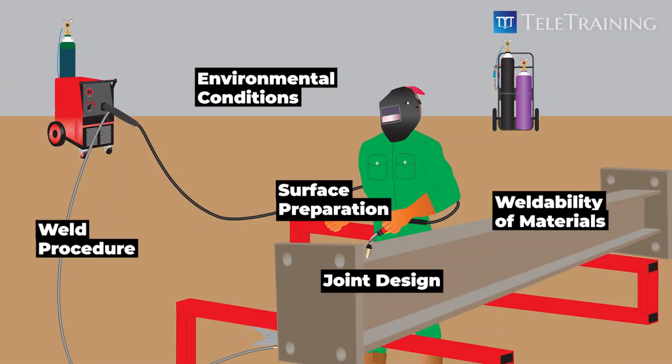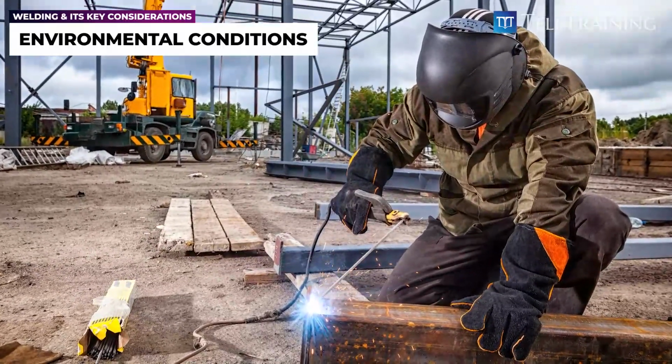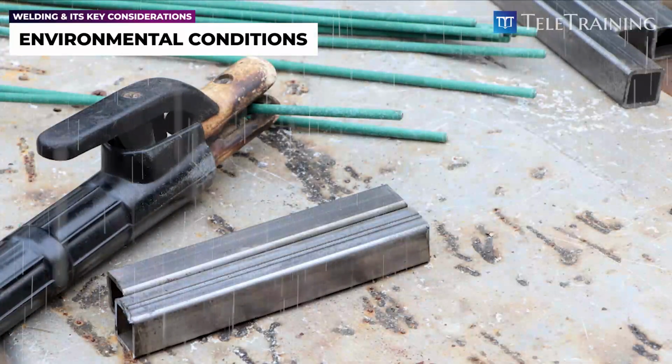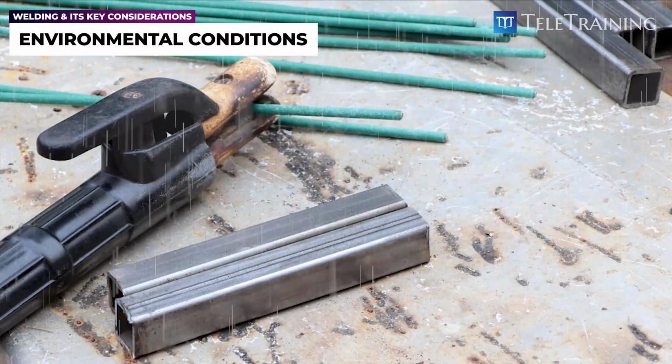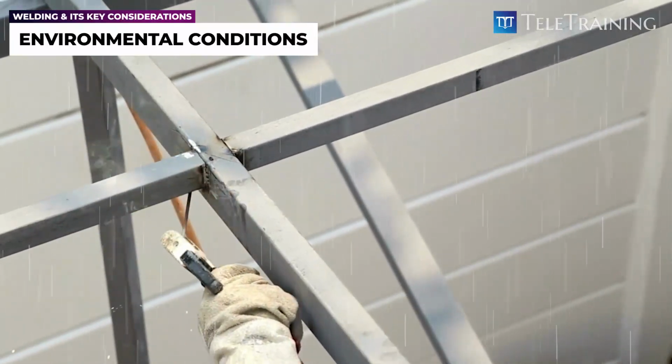The next is to consider environmental conditions. Environmental condition is a very critical factor, especially for welding on site. For example, moisture could impact the stored electrodes or consumables on site. And with too much moisture, they won't melt consistently during the weld.